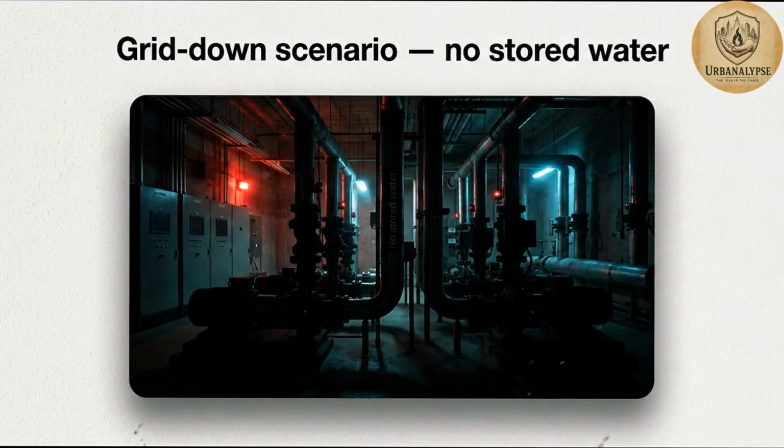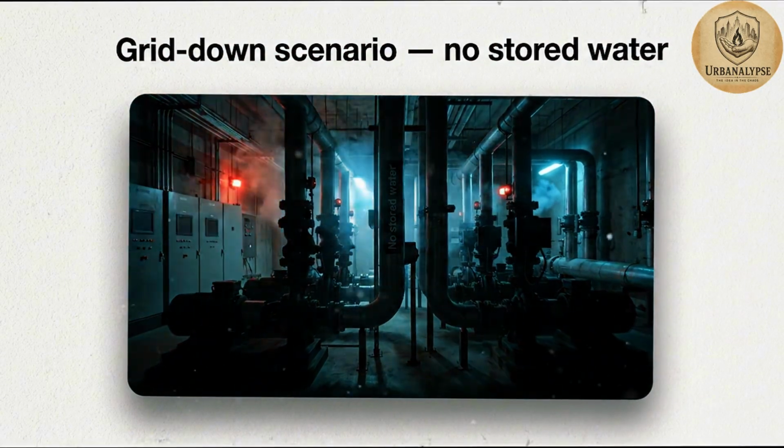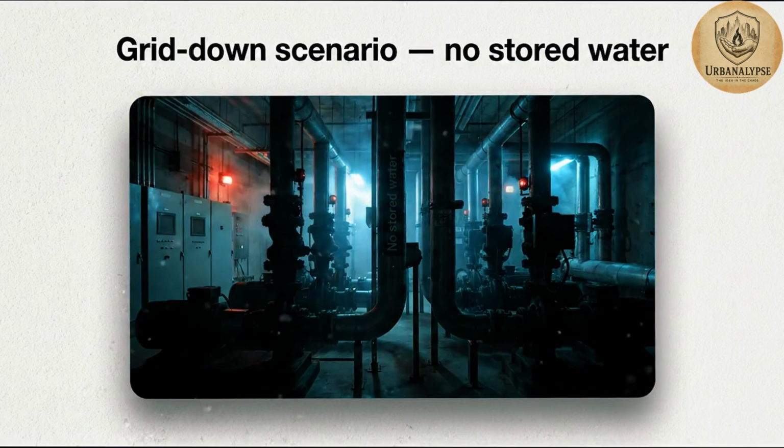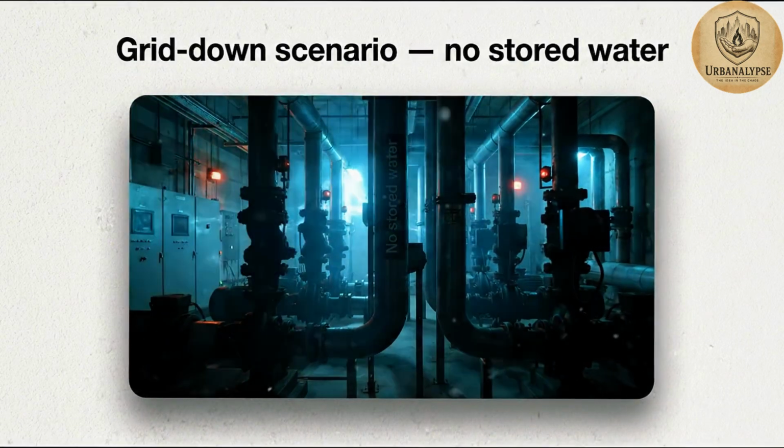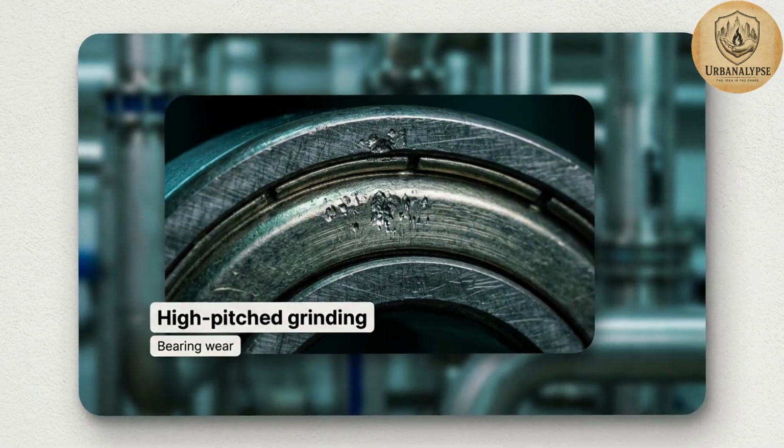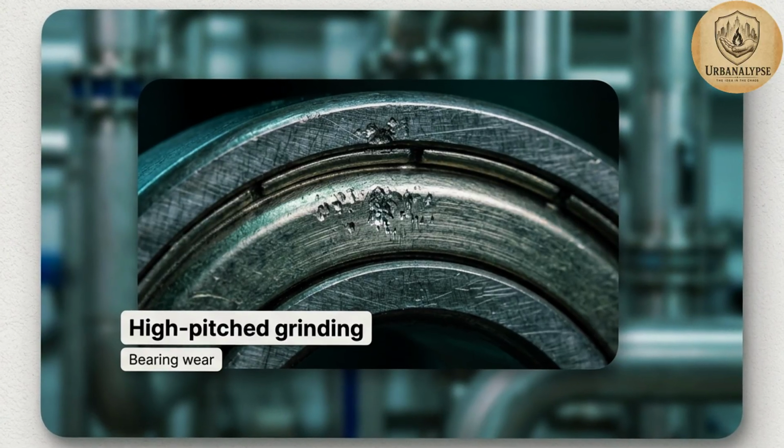A grid down event hitting this failure with no stored water is the exact scenario we document to prevent. I have heard that sound. High-pitched grinding from the booster room attributed to bearing wear.